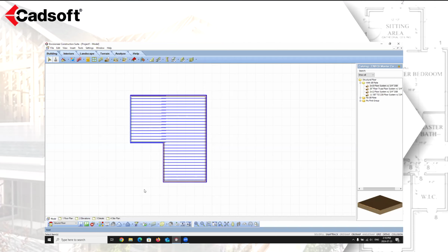So after you've inserted your floor by using the floor by room, floor by perimeter, or floor by picking points option, you can select it and then right-click and select its properties. So we inserted a structural floor. But let's say we want to add in our own floor off in a different room. We can do, again, floor by room, floor by perimeter, or floor by picking points.